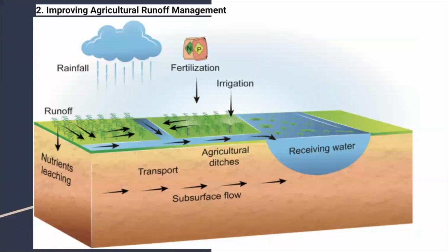Next, agricultural runoff often contains a variety of contaminants, including pesticides, herbicides, and nutrients such as nitrogen and phosphorus, which can degrade water quality. By studying the adsorption capabilities of materials like activated carbon and nanoparticles, this research can lead to better strategies for managing these contaminants at their source or during their transit in waterways. For example, enhanced filtration systems could be designed based on the data obtained from such experiments to be installed at critical runoff points.